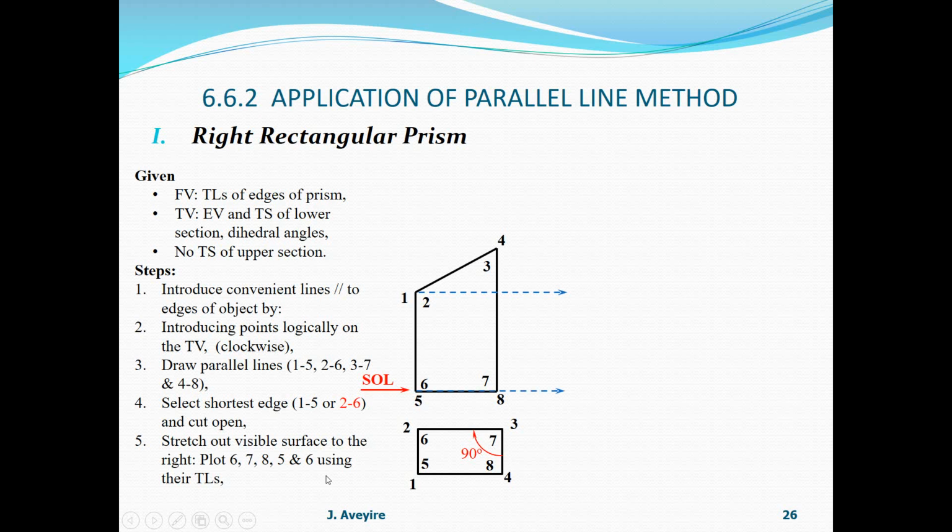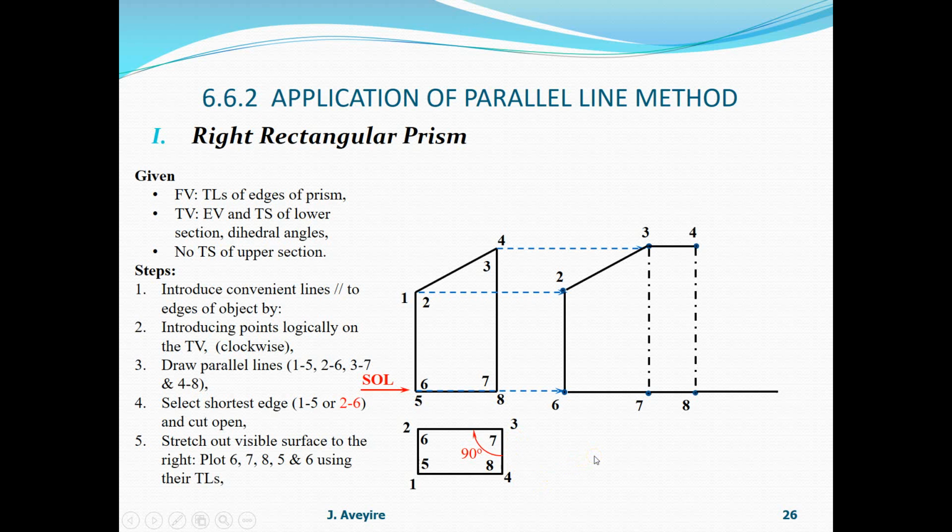Projection. Here, first of all, we have point 2, line 2-6. Then we move on to 7. For 7, we take the true length of 6-7 from the top view, put it over there, and we obtain 7. Then the height of 7-3, we plot that to get 3. We draw the line to join them. Then the perpendicular distance between 7 and 8, so 8 is plotted. Then the height of 8-4 by projection we obtain, and then the dash, that's the edge given.